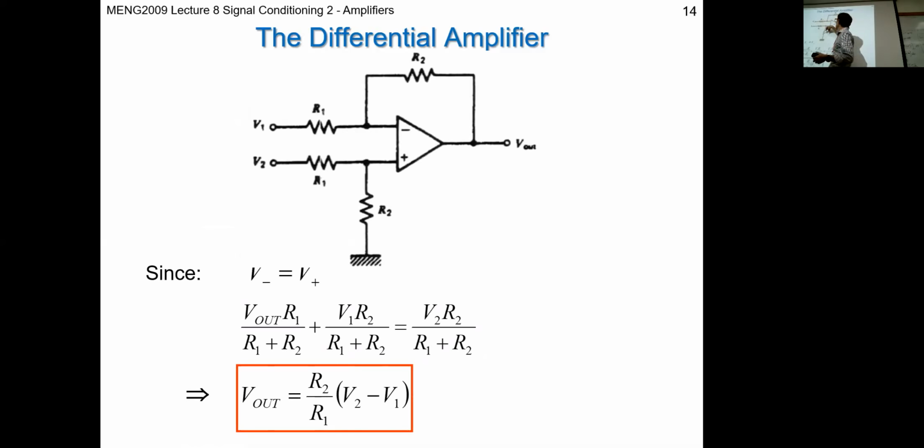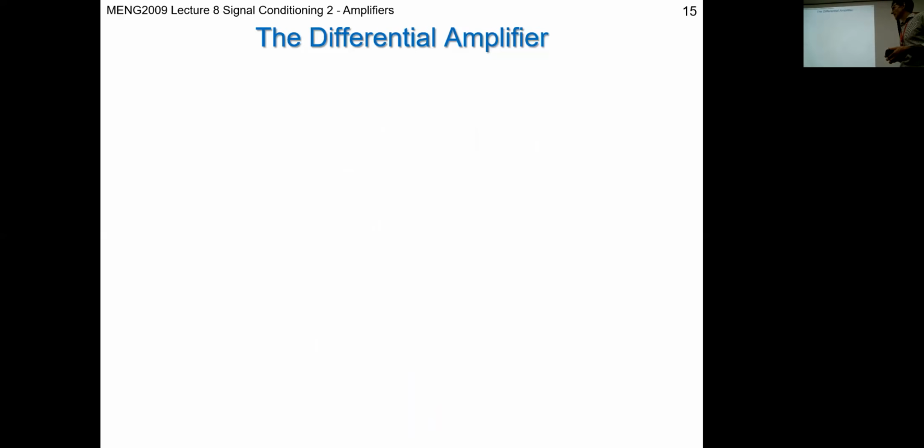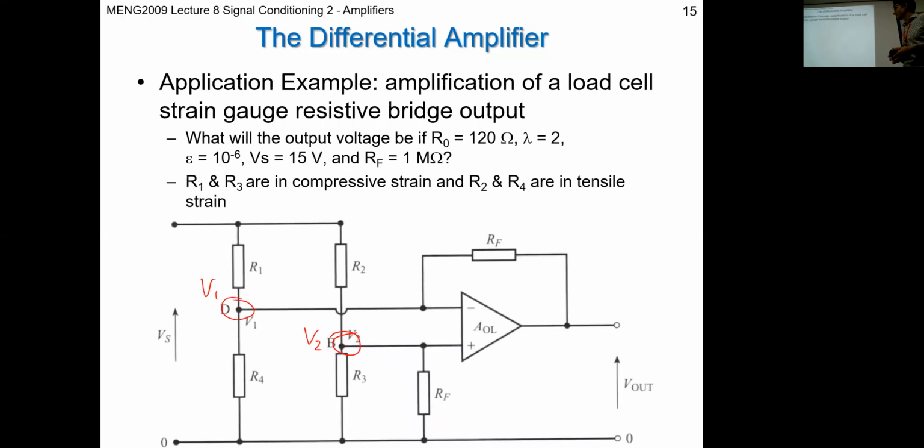And the feedback and ground resistance are matched, and the two input resistances are matched as well. But in this case, what's our input resistance? What's our R1? Well, we know what our feedback is, and we've got our ground resistor there. But how do we define what R1 is? That's a little trick with this particular problem.